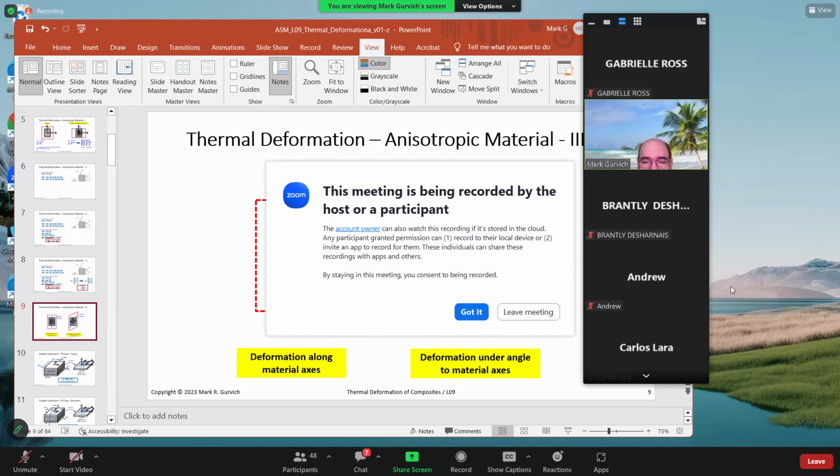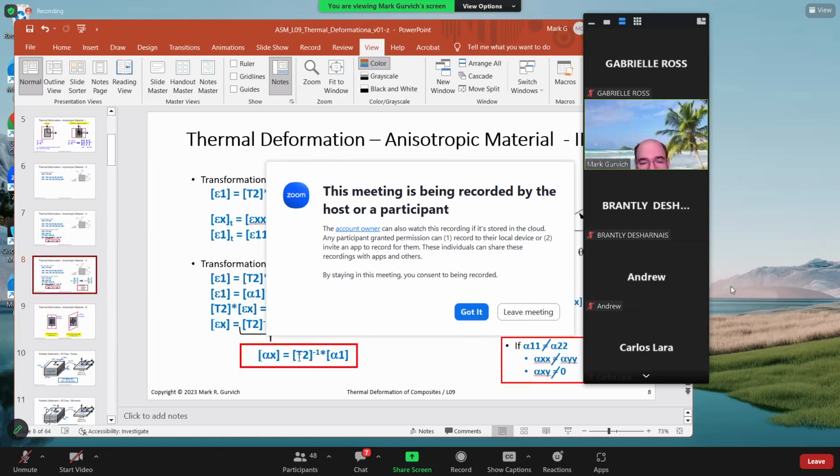So, ladies and gentlemen, any questions or comments so far before we move to laminated analysis? Because laminated analysis will have a lot of math in addition to physics. I want to be sure that thermal deformation for a homogeneous but anisotropic body is captured very well. I would say the major conclusion is that if we know thermal properties in one orientation, we can recalculate the material thermal properties in another orientation, XY. And we can also do it in the opposite direction.